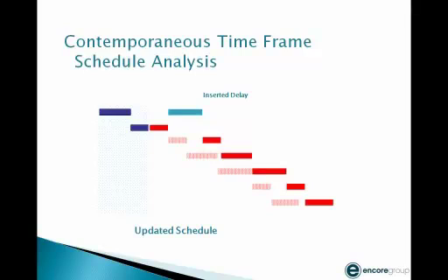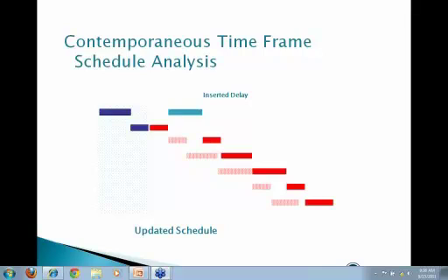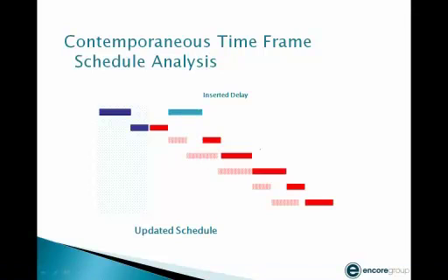And the argument for that is, if our budget as the owner is 300 days, and you say you can finish it in 250, that means as an owner, I'm going to have to reallocate my budget and spread it over 250 days instead of 300 days. So if I do that and I've spent all my budget by day 250, then I'm going to have to spend extra money if you don't meet that 250 days. So it's very important. If you want to meet it in 250 days, it's very important you do it, and we're going to give you a change order to make sure you do that.